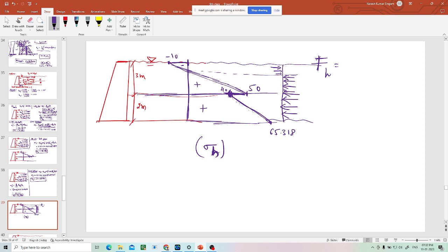It's like that. Let us say this is the wall, and now there is clay or something behind. What happens now? To push this wall, there should be contact between this earth material and the wall. So what is happening is that this particular soil, until this depth, is not pushing it, it is pulling the retaining wall towards itself.